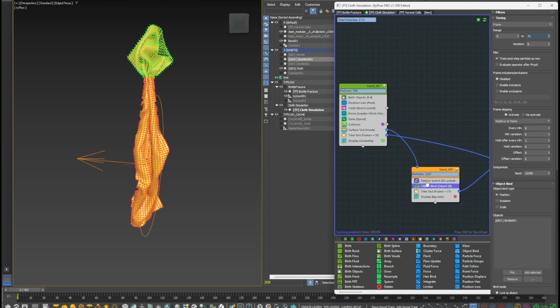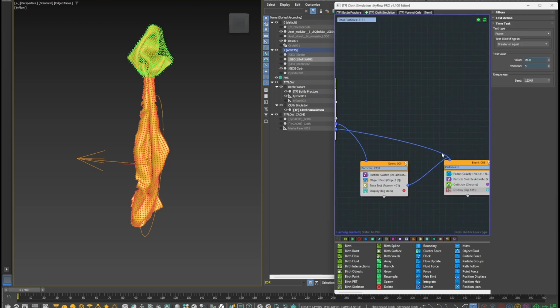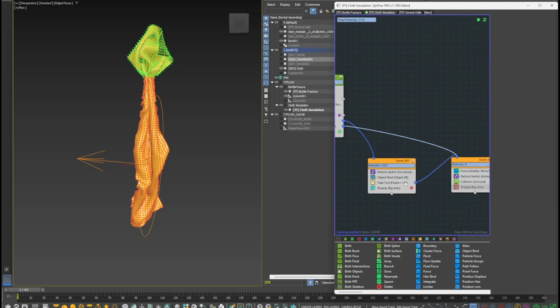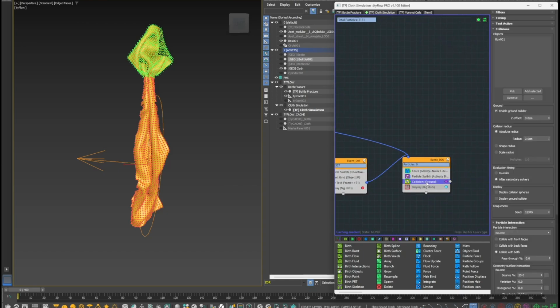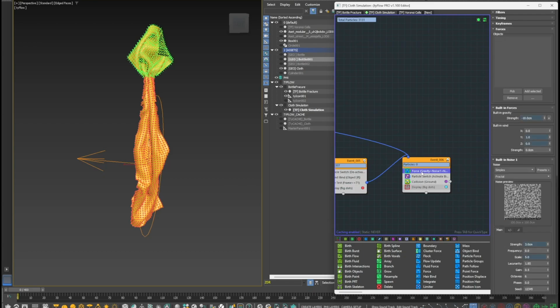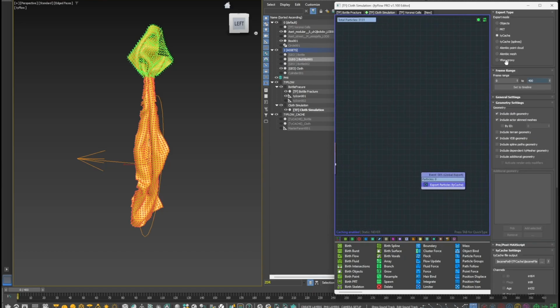The upper part, the one that is outside, is left in the first event until frame 70, then sent into another event. In frame 71, the inactive part is also sent into the same final event that now has the entire cloth active again, and there is a collision with the column and the ground being applied, as well as some gravity force. The cloth is exported as a separate TyCache that has the Include Cloth Geometry option enabled.